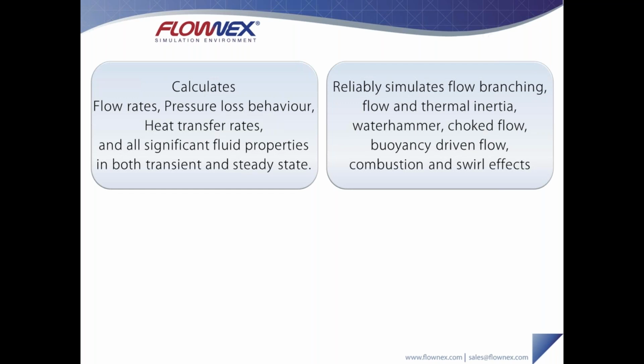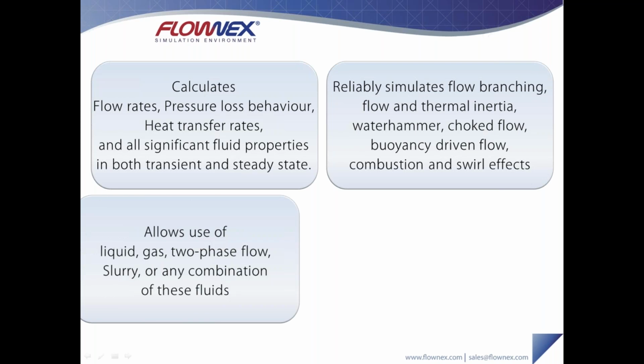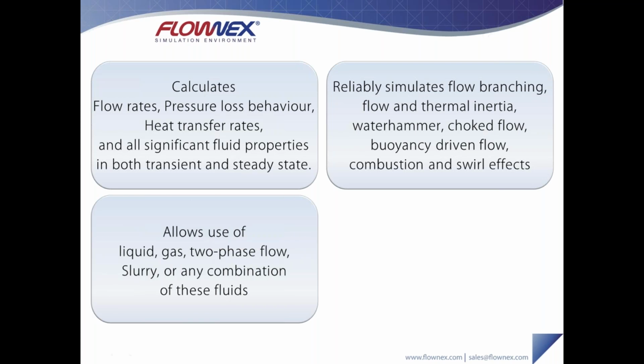And all of these make it perfect for simulation of, let's say, for example, power plants where you have startup and shutdown scenarios, and you need to include the inertia of the turbo machinery or the pumps, and then also of the fluids itself. It allows the use of liquids, gas, two-phase flows, slurries, or any combination of these fluids. So I can mix water with air, and then Flownex will enable me to calculate the correct fluid properties.